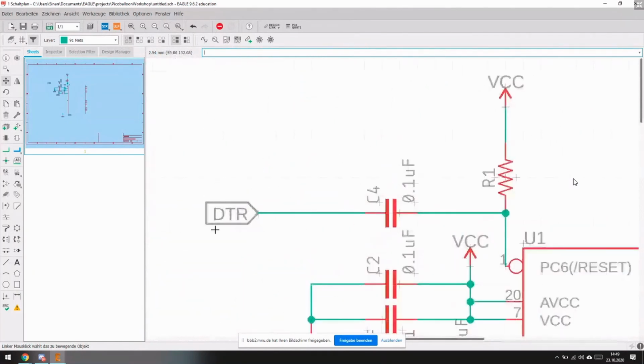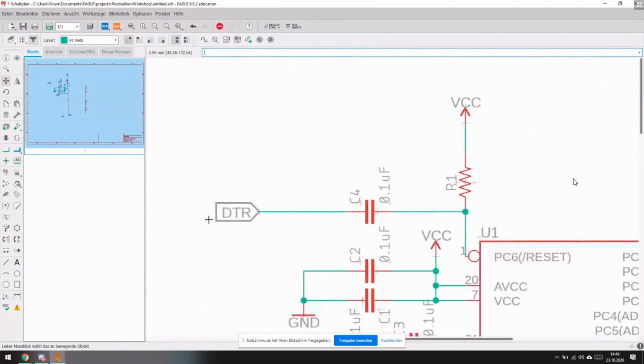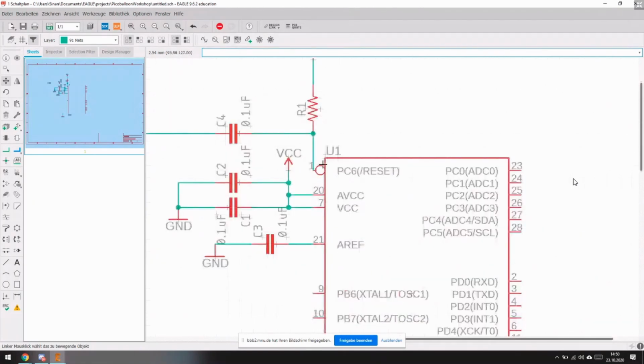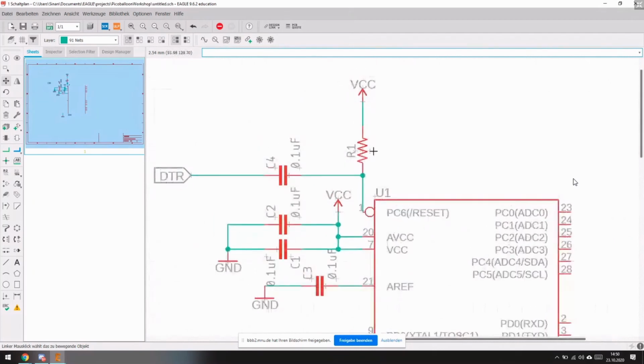If we connect this DTR to ground, or to minus, so to speak, then electricity takes the path of least resistance. That's not the whole story, but it suits our purposes here. We connect this to ground, then we will pull that low. We will pull the pin low.